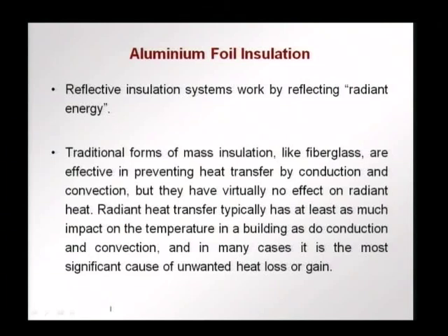and radiant heat transfer is very important, as important as conduction and convection on the temperature in a building, and in many cases it can become the most significant cause of unwanted heat loss or heat gain. Heat gain in the sense that heat from outside the building penetrates, or heat loss in the sense that you have a cold environment outside and you want to prevent heat loss from within the building through some artificial heating, and this heat should not be lost.